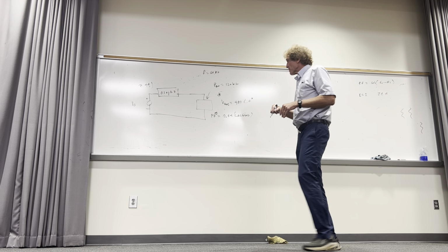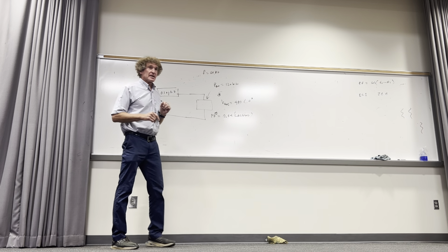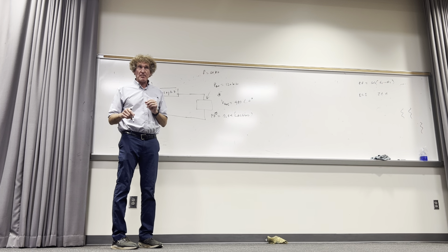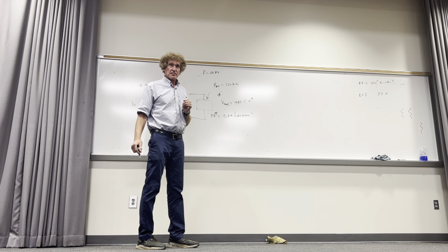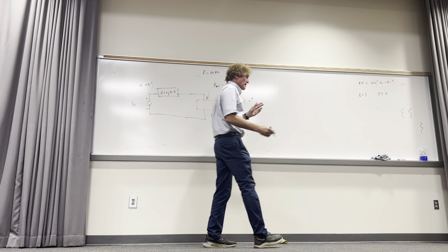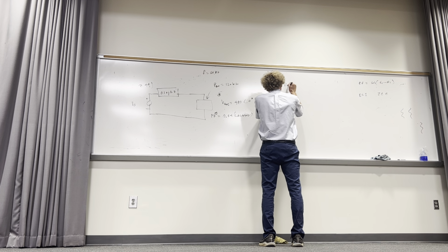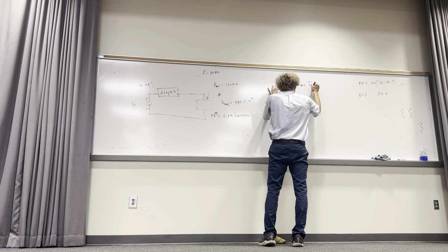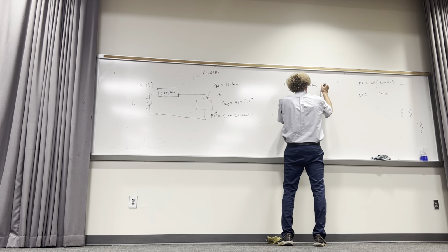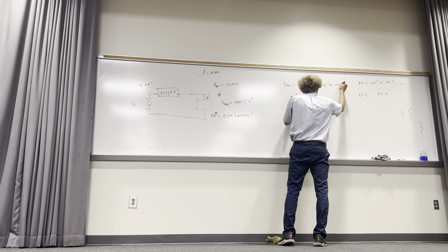Please be attentive here. For this one, they give us 120 kilowatts that's being used. Y'all follow me? And you'll notice the voltage is an RMS, unlike peak. So if you think about the formal definition, P_av is equal to V_RMS times I_RMS times the cosine of theta v minus theta i.